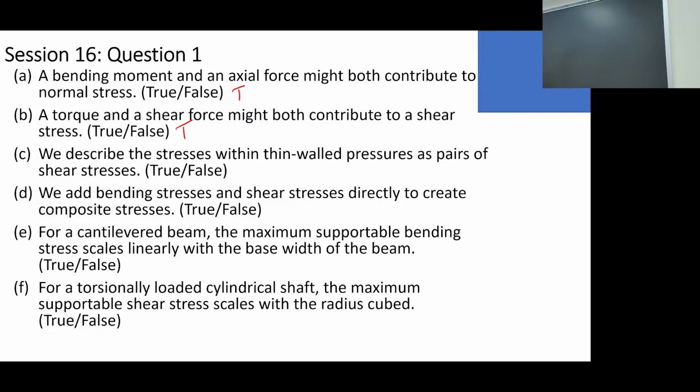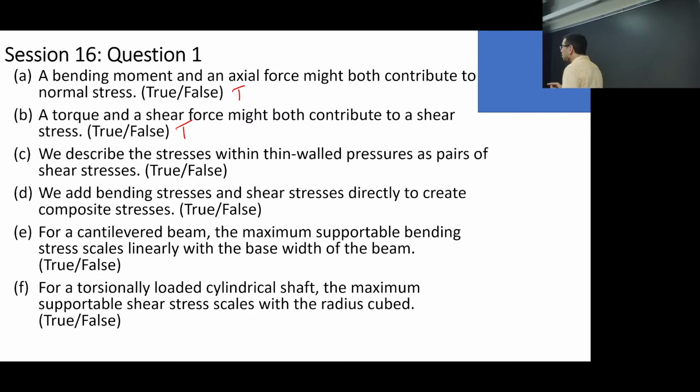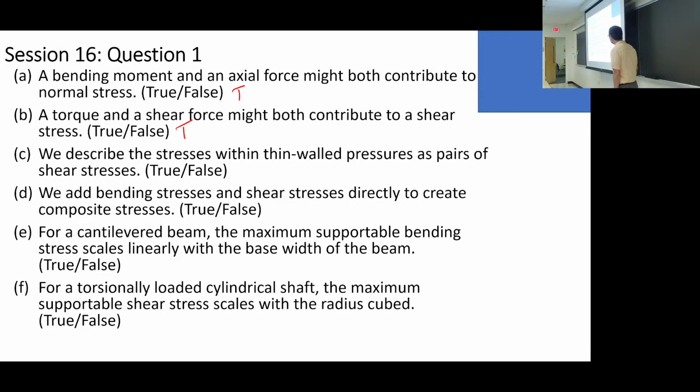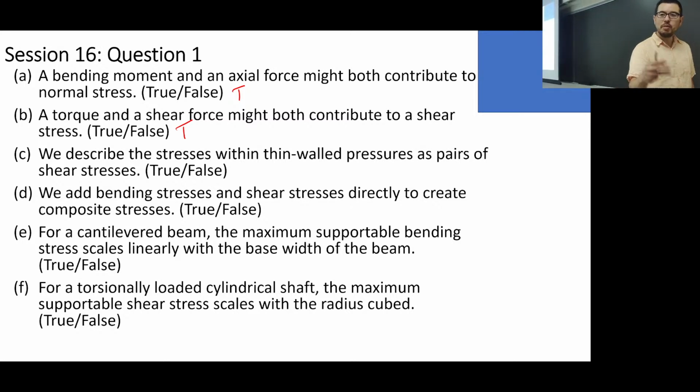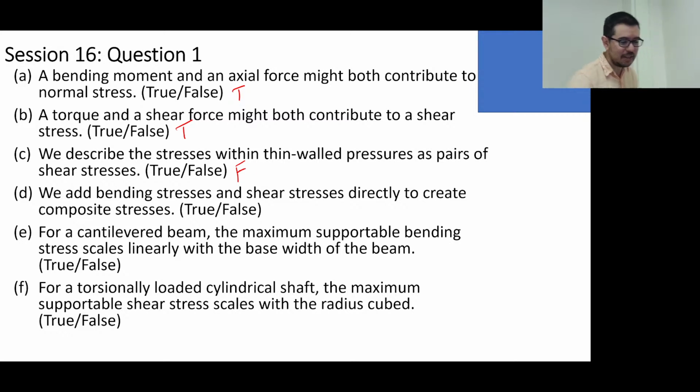So shear stresses, we don't have any equations for shear stresses within thin wall pressure vessels. Not yet. We will talk about the equivalent shear stress in a thin wall pressure vessel, but we don't think of it in terms of pairs of shear stresses. Typically, we describe them in terms of normal stresses. We can convert them to an equivalent shear stress, but yeah, that's good. So this is false.